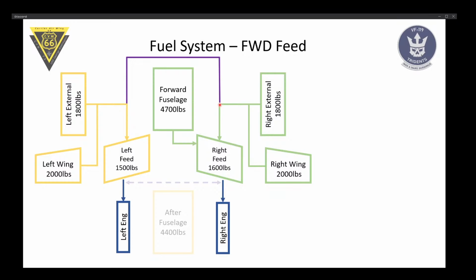The wing and external fuel lines get connected into one fuel line, and the so-called sump-tank interconnect valve opens. This basically connects the left and right feed tanks, and the flow direction, which here is in the left direction, but generally the flow direction will be governed by whichever tank has more fuel, because this is purely pressure head